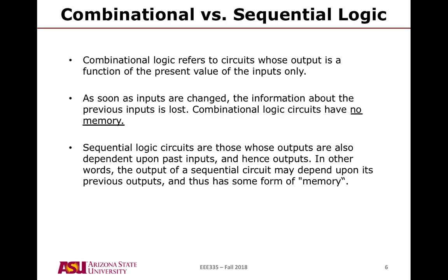The difference between sequential logic circuits and combinational logic is that sequential logic can store a state, meaning the outputs could either be dependent on the present state of the inputs, or they can hold their past state, so they can remember, which is the form of memory.